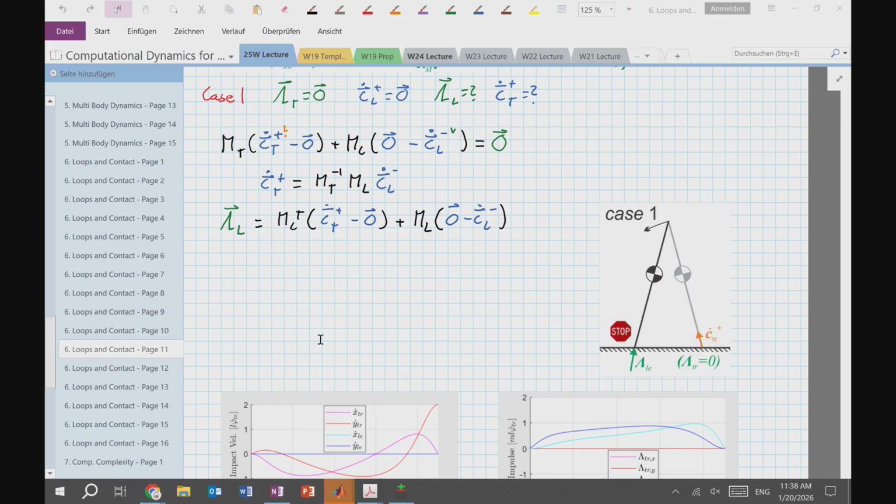So a ball and socket joint, of course, if everything is planar, inertia, mass distribution, everything is planar, initial conditions, it should behave like a rolling contact, like a revolute joint around 2 axes. And that way, right, you can check everything, start with simple things, see, okay, do I get this? Do I get that? What happens if I get a motion about the longitudinal axis? And very carefully build yourself up, right?